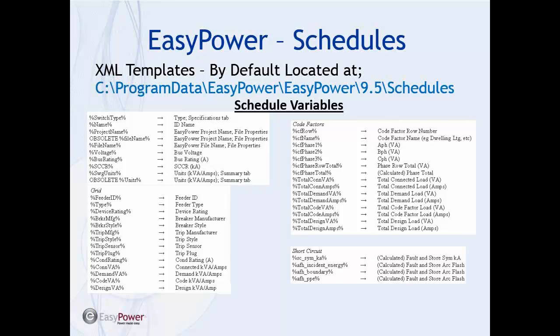So anything that includes a rich text format, you're going to end up supplying some garbage of sorts, I guess, for lack of better words, into the templates when you save it. So it is really important to make sure that you save it with the panel or with the schedule extension that you're specifying. And it is a text document, so make sure you don't save that as a rich text format.